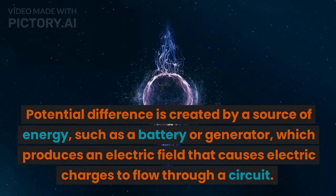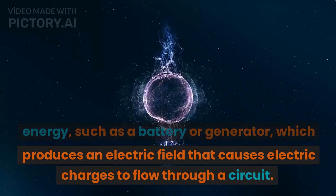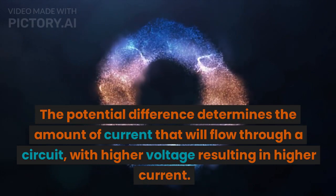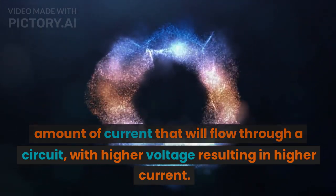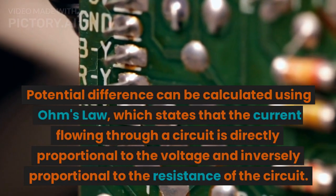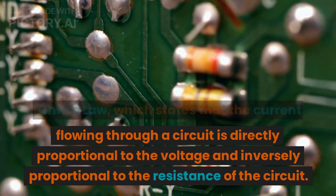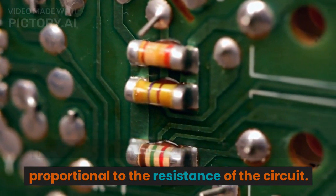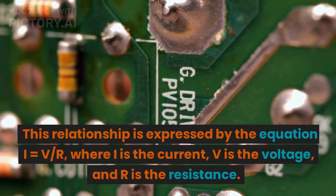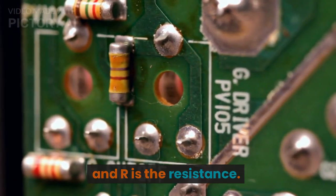Potential difference is created by a source of energy, such as a battery or generator, which produces an electric field that causes electric charges to flow through a circuit. The potential difference determines the amount of current that will flow through a circuit, with higher voltage resulting in higher current. Potential difference can be calculated using Ohm's law, which states that the current flowing through a circuit is directly proportional to the voltage and inversely proportional to the resistance of the circuit. This relationship is expressed by the equation I equals V over R, where I is the current, V is the voltage, and R is the resistance.